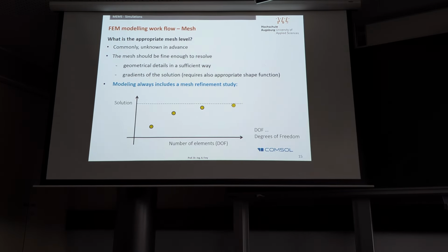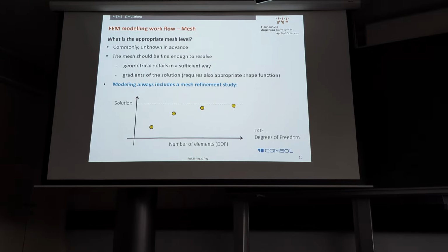But maybe that is one of the things, interestingly enough, that people doing simulation work sometimes, amazingly often, forget. That should be part of any modeling. You should make such a mesh independency study. Without doing this, you're not finished. If you set up your models, you will see you can quite quickly provide some simulation results, but this has to be verified.